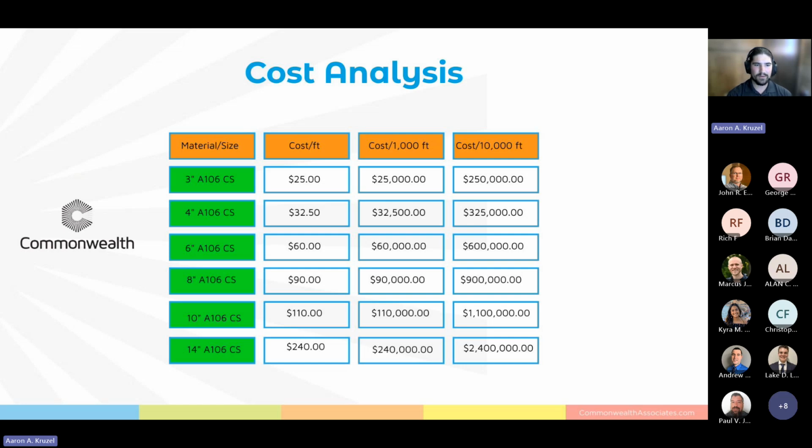Something I didn't show in Arrow is the clone feature, the child feature, basically creating a base version and then subsequent versions of the different cases that your plant or system would experience. So accounting for the high flow state or the low flow state, you're able to do it all in the software, and then using hand calcs to back it up, making sure you're not just relying on the software, you can 100% validate the system will work in every situation. Doing that by hand is prohibitive by time. You don't have the time to do that. But with the software, with AFT, you're able to.